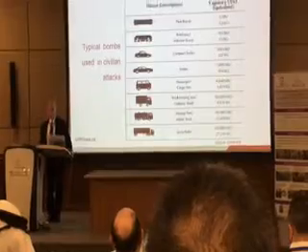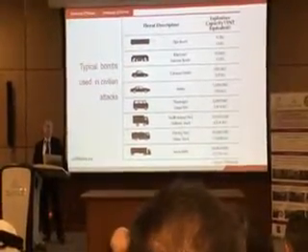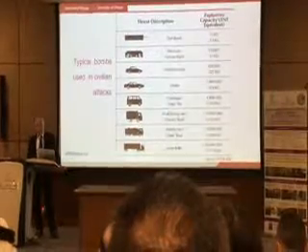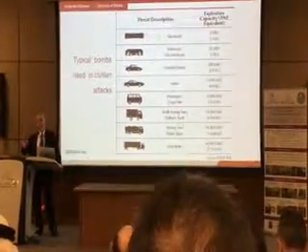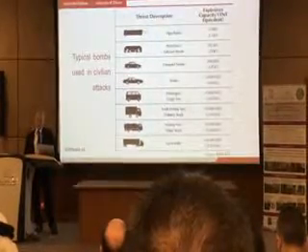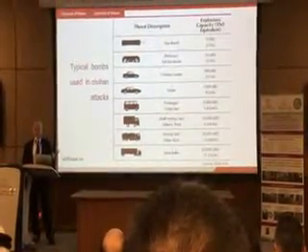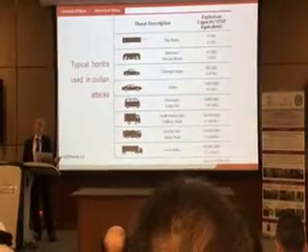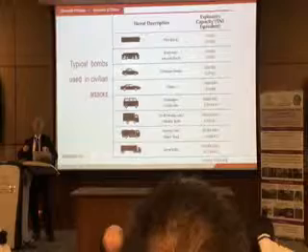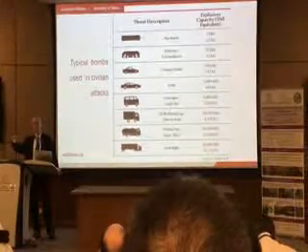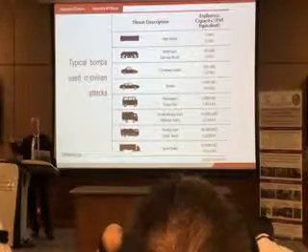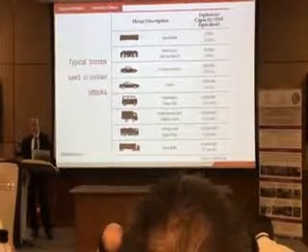In terms of typical civilian bombs, they range from pipe bomb, which is putting TNT into a steel pipe, to suitcase or backpack bomb, and they are usually 20 kilograms, so whatever someone can carry comfortably in a backpack, and they usually leave it right next to the structural member, so there's a close-in explosion or contact charge.